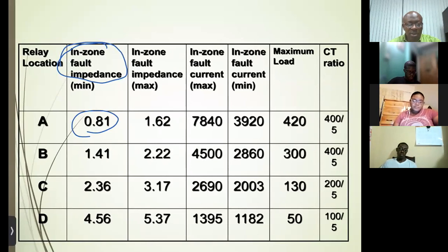So it's 11 squared over 150 MVA. And we get 0.8. It's not exactly 0.81, but I wasn't very keen on maintaining the standard as far as the decimal place is concerned.